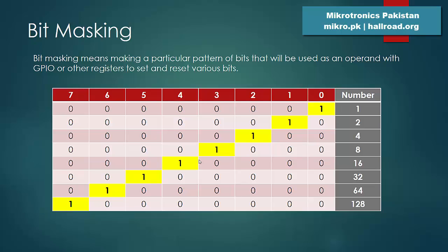In 16-bit computers, it's 2 bytes, and in 32-bit processors, it is 4 bytes. So your microcontroller will be performing the operation on the entire 32-bit word. It is not possible to directly address a single bit of the 32-bit registers, so we need some logical operations to set the individual bits.